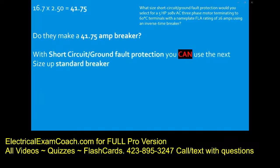I want you guys to know that with motor short circuit ground fault protection, you can use the next size up standard breaker. When we get to motor overload protection, you cannot. So with short circuit ground fault protection, you can use the next size up breaker. So we head to table 240.6(A) and we find a breaker that is the next size up from 41.75 amps. And in this case, it's going to be B.